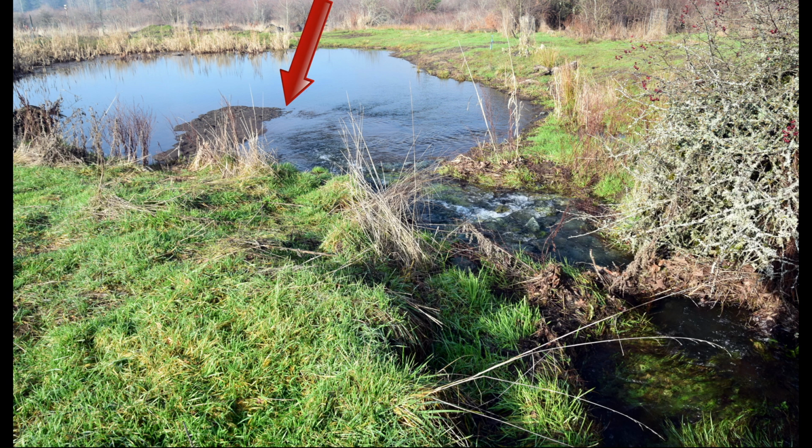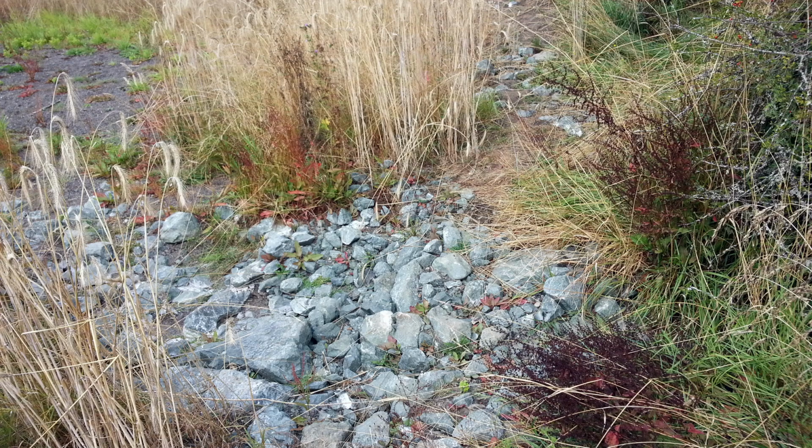The red arrow points to sediment that's settled in the new wetland. The wetland filled with soil after only 2 years of construction because of the great amount of erosion taking place upstream. We had to remove the soil using an excavator and a dump truck. The buried vertical grade control structures have controlled the head cuts and have prevented new head cuts from forming.